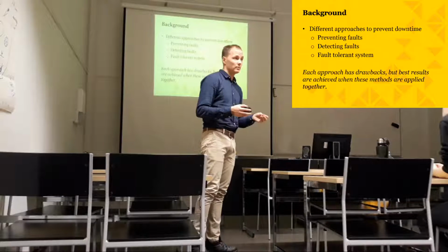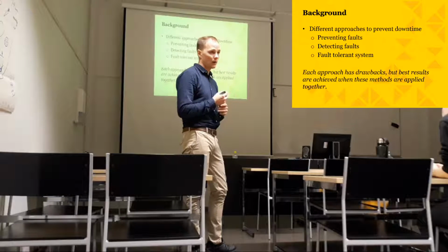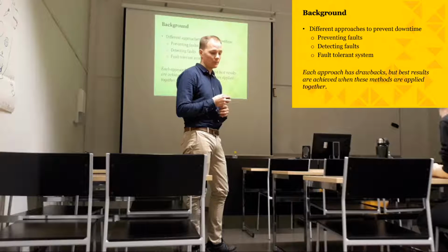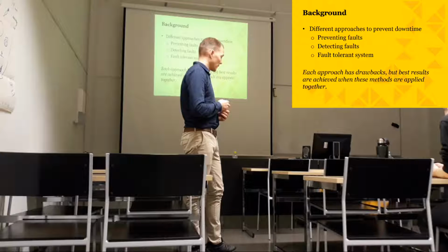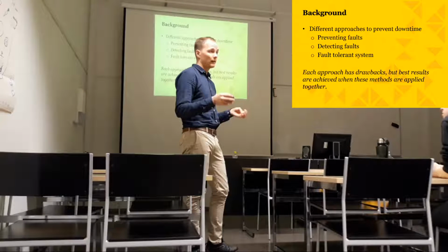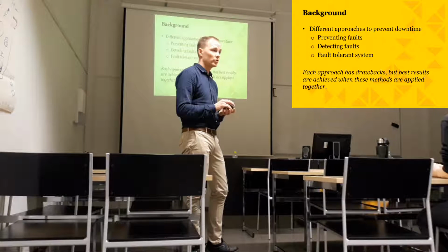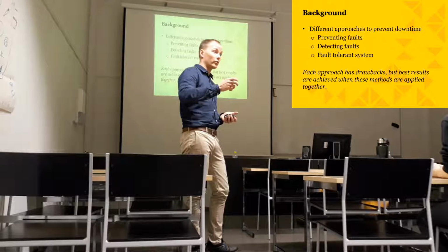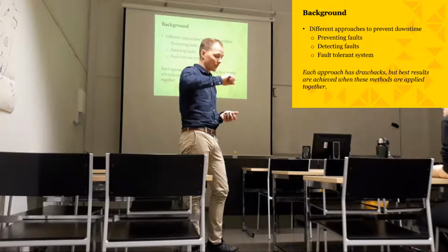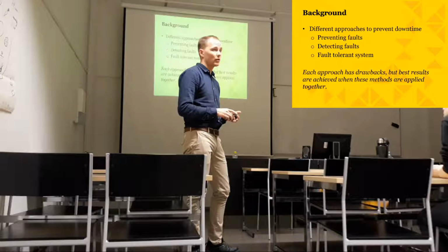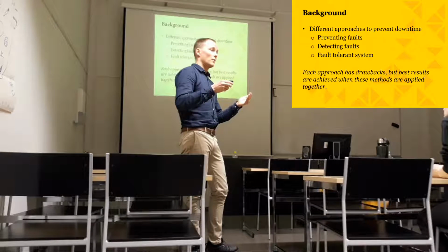Detecting faults is what we are addressing here. There are also other ways to detect faults in electric motors. Methods based on vibration: there's a sensor attached to the shaft of the electric motor, and there are also methods based on acceleration.